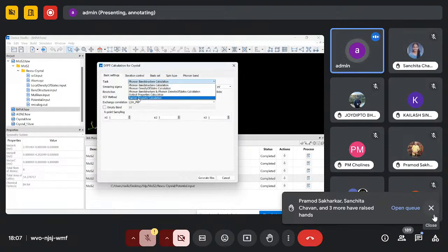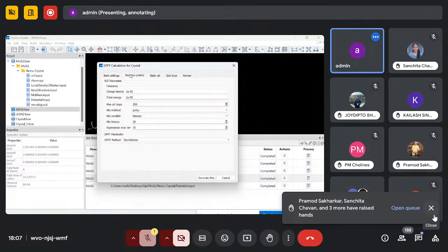For this analysis, let's suppose I want to calculate the Raman property. So I selected the Raman default parameters, and this is smearing, sigma, resolution, and the real space method in this DFPT. There are two options, LDA and GGA, for Raman calculations. Iteration control is there, and this is the DFPT Sternheimer and CFSI. These are two solvers that will solve the perturbation theory.